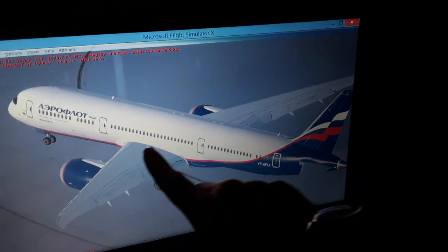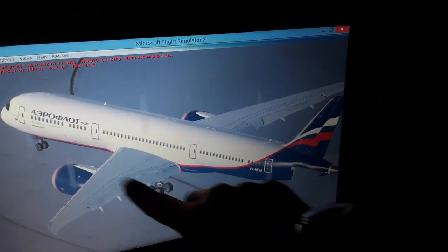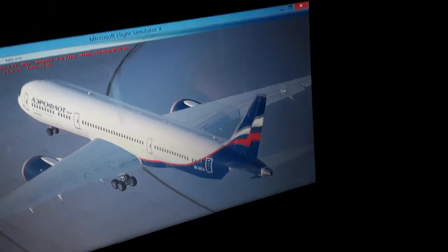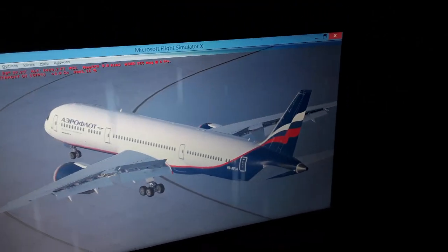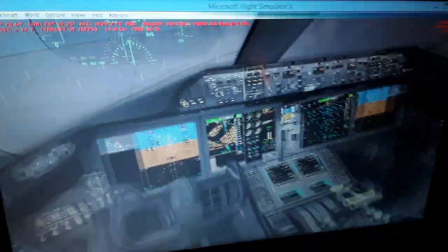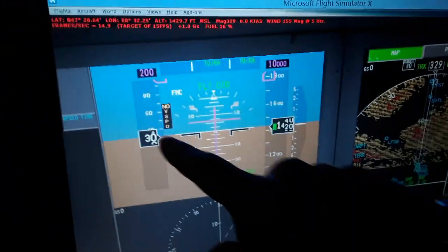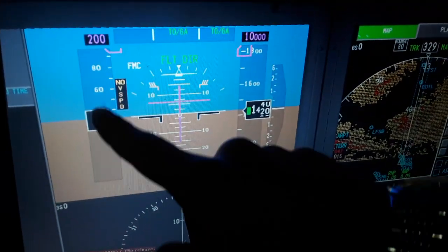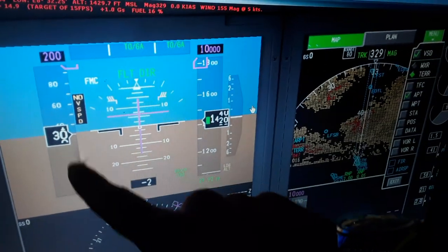And we also have the stall, which will occur over here, at the mean aerodynamic chord at 23% of the MAC. In the stall, the airflow becomes detached when we fly. So you will notice when we fly, the stall is going to be displayed in the primary flight display over here. You can see the primary flight display, we have the airspeed indicated, and the stall speed is going to be displayed with yellow and red indications below the airspeed as we fly.